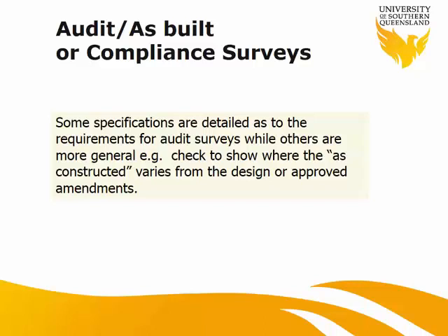So moving on, the next bit we want to talk about is the as-built or compliance survey. We all know about the as-constructed, as-built survey. Basically, this is the survey we do at different stages of the construction project to make sure that we comply or conform to the design specification and standards. It's pretty much the same, just different terms; as-built survey and as-constructed are pretty much the same. So it's basically to check that the as-constructed work meets the design specification.